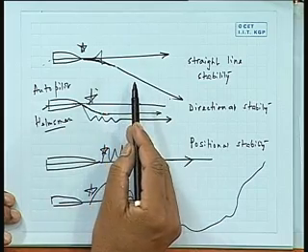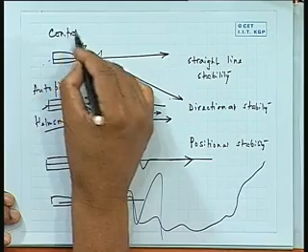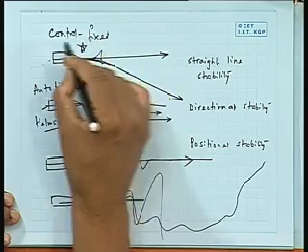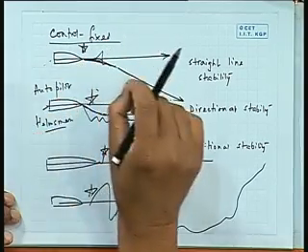In other words, a ship without any control, this is what is called control fixed. If you do not have a control surface operating, at best what you can have is a straight line stability. In other words, you have a rudder frozen, okay, the ship is going, you give a disturbance, it takes another direction and it keeps going on a straight line.